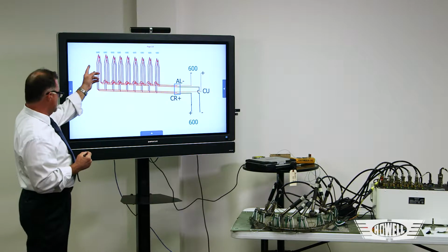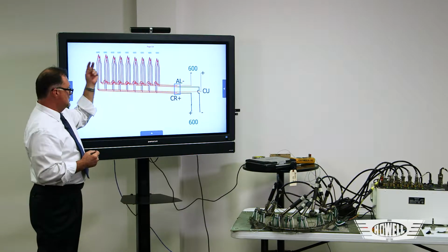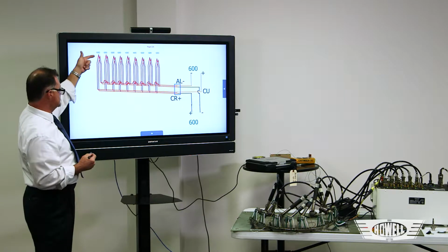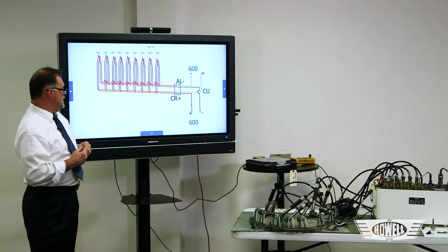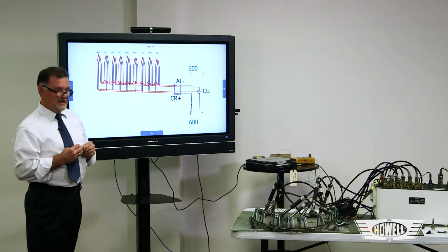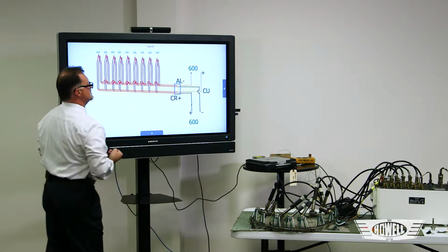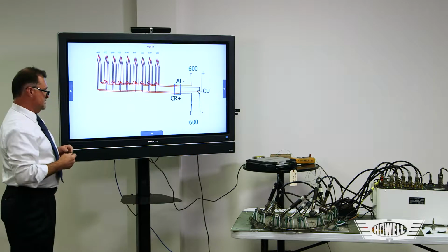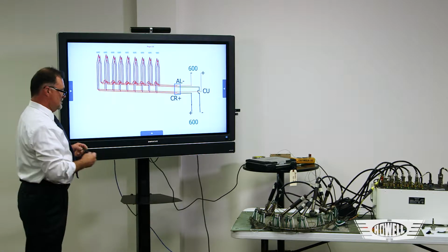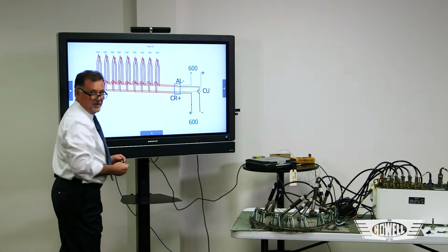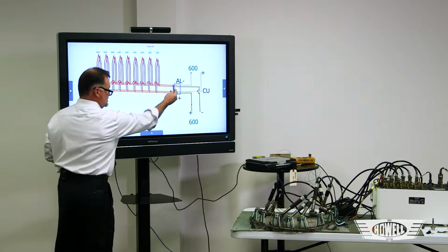So as I'm set up here, I have 9 thermocouple junctions times 2. I've got one set for the TIT indicator, and I've got one set for the temp datum fuel control. What you see over here is collectively the Alumel, which is the negative potential of this millivolts DC, and then Chromel, which is the positive. Here is known as an iso block.